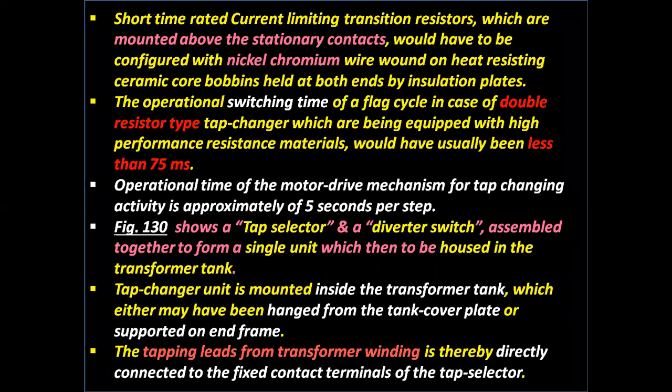Short time rated current limiting transition resistors, which are mounted above the stationary contacts, would have to be configured with nickel chromium wire wound on heat resisting ceramic core bobbins held at both ends by insulation plates.